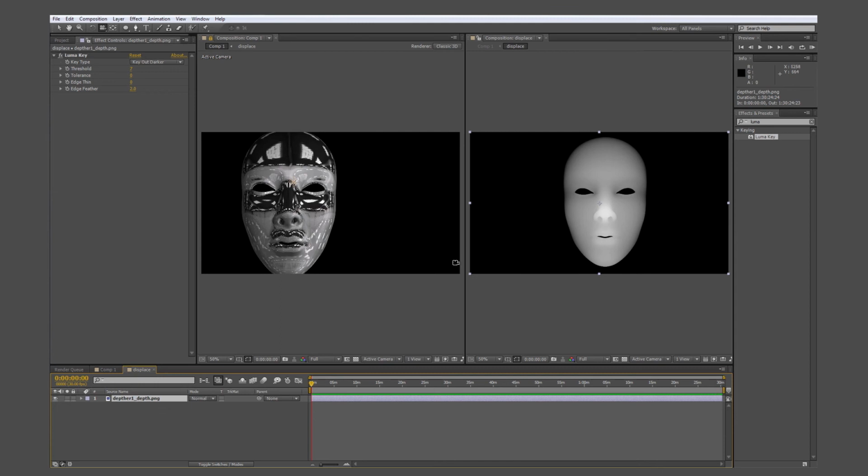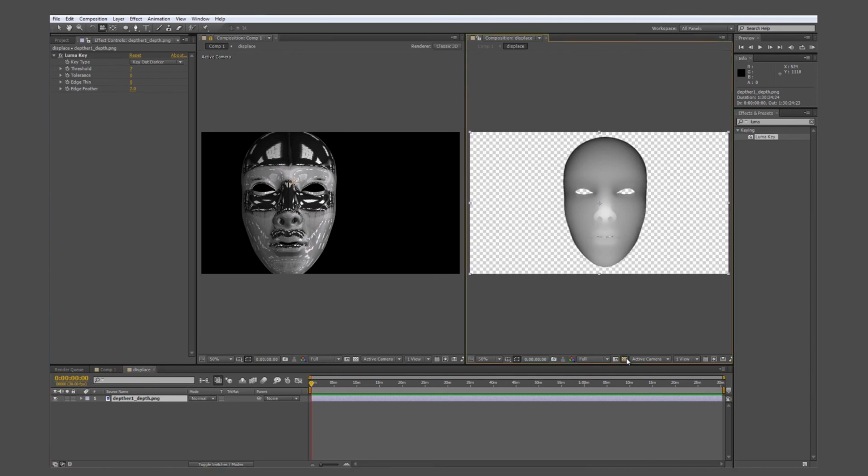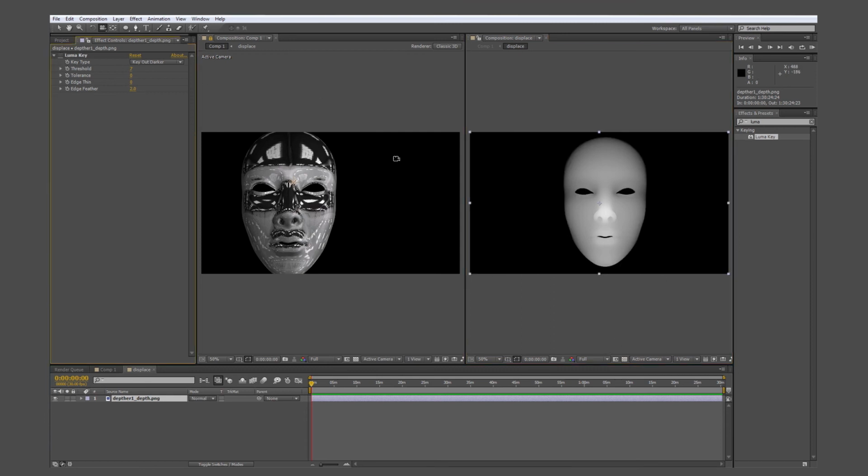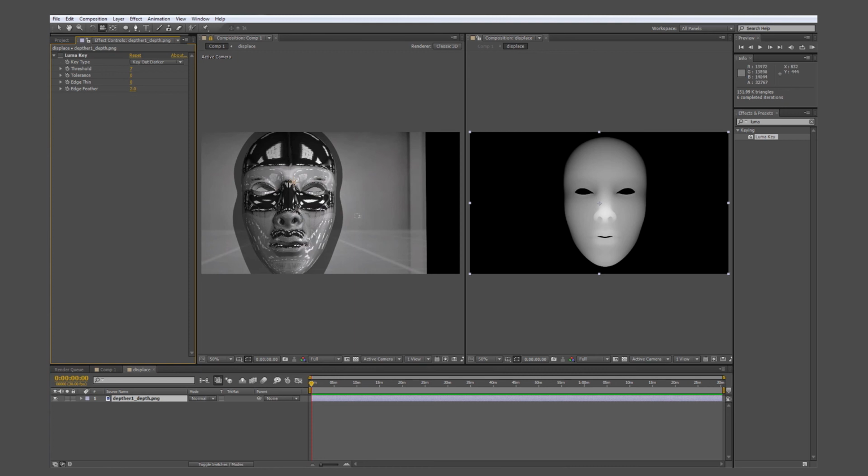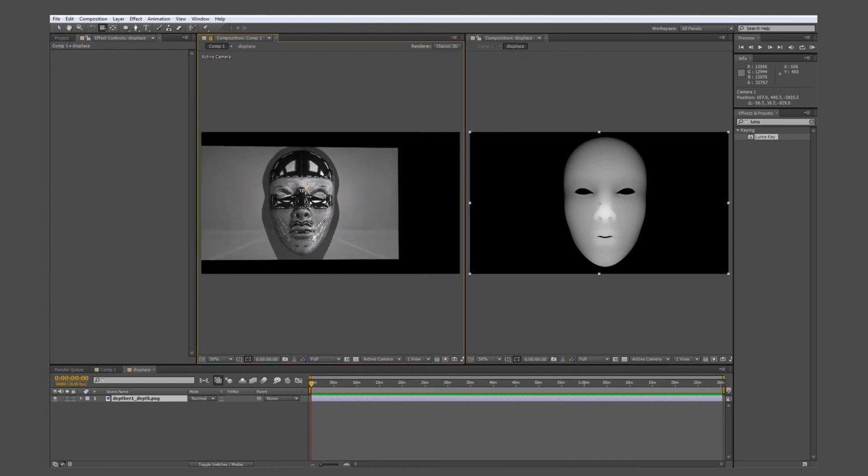And what we're going to do is change the face to the red channel, and isolate the background as a blue channel. Now at the moment I have the Luma key on, so you can see that there is no luminance value here and it's transparent. I'm going to turn that Luma key off and we can see the background reappear here, which is what we want.